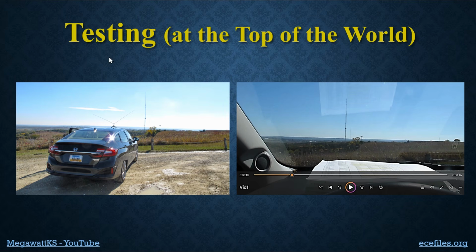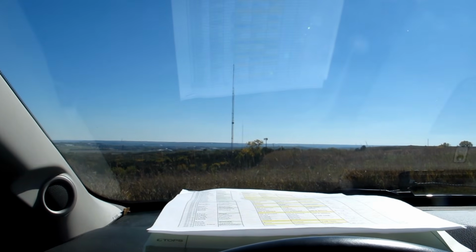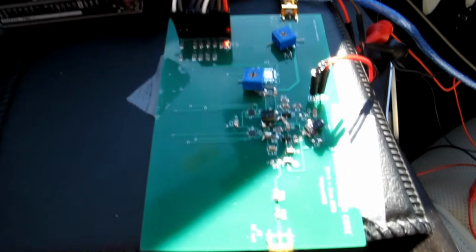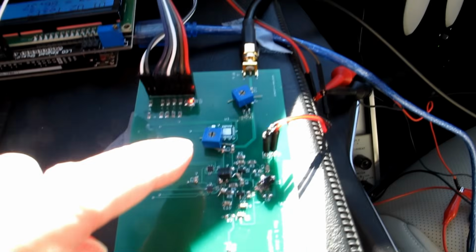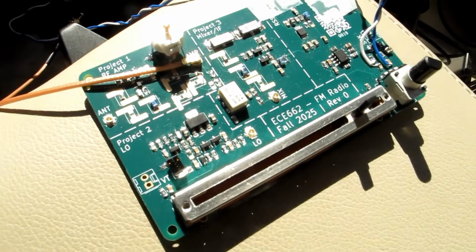And lastly, here we are outside again, but we're now at top of the world where all of the signals are bigger, and the one that's on this tower, which is 96.3 FM, is huge. Okay, we are at the top of the world. There's that big antenna over there at 96.3 pumping a huge signal at us. And we've got our Q enhanced filter here. I set up a little bit of attenuation on the front end, not too much, and dialed in some Q enhancement, and we're picking up 88.1, but it's coming from our radio, out of these speakers.